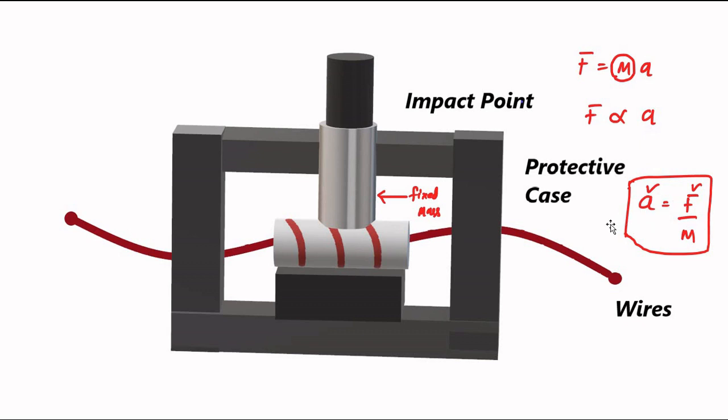So when it is calibrated to measure force, the output will be given in terms of newtons. When it is calibrated in terms of pressure, the output will be in newton per meter square, or pascal, or bar. Then when it is calibrated to measure acceleration, the output will be given in meter per second squared. So it's up to the manufacturer to decide in which way to calibrate it, but the operating principle is the same.